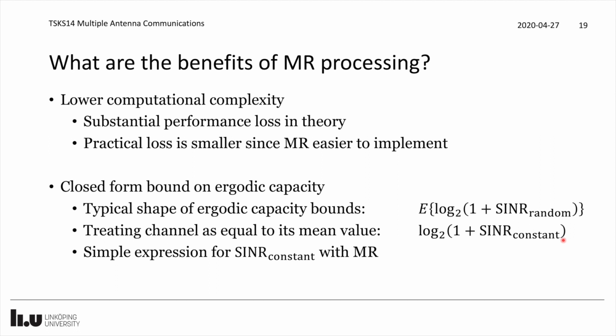We can understand the different parts: how the number of antennas is affecting the capacity, how the large-scale fading coefficients and the estimation quality come into the picture, the interference, everything is there in a neat form. So this is a very useful way of understanding the ergodic capacity behaviors when we are dealing with massive MIMO.